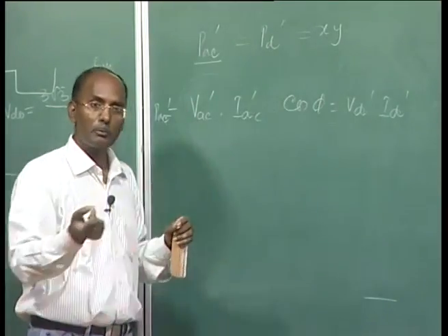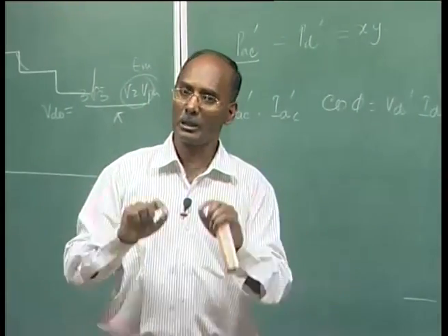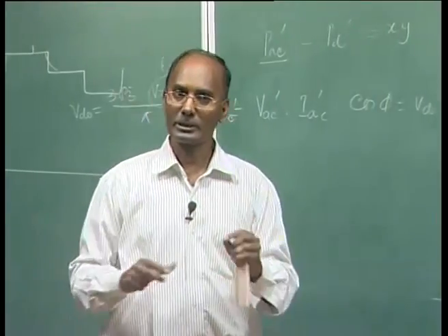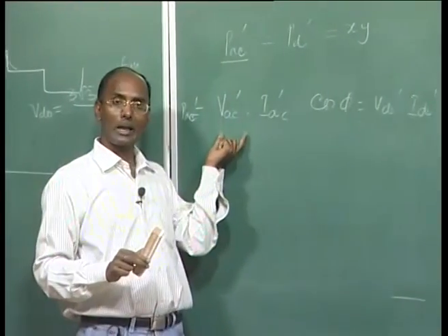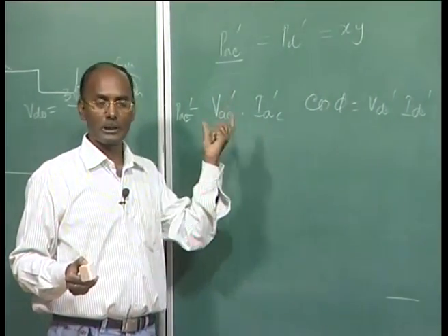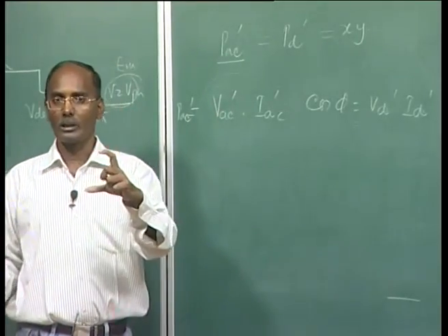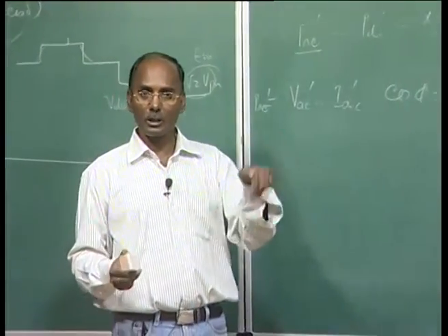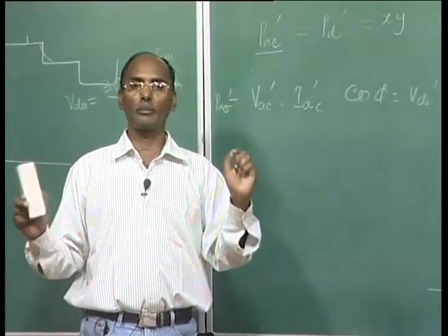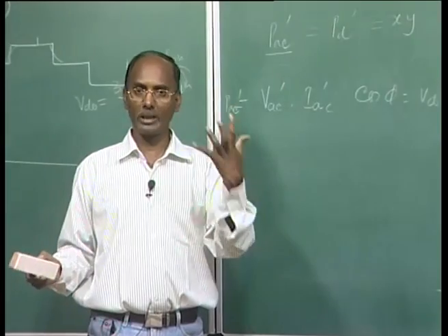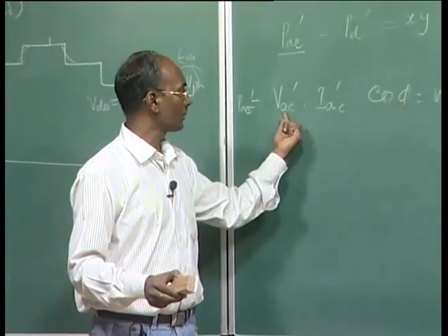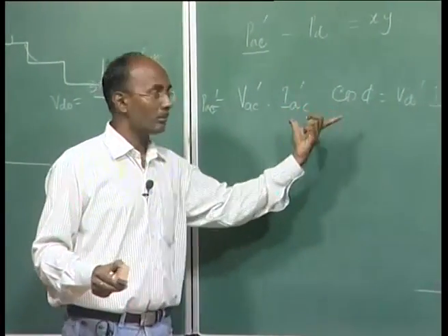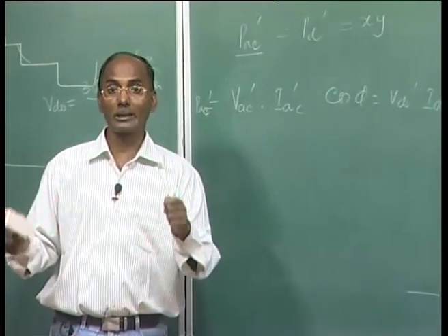So in per unit the three-phase concept has gone, it never appears. Because simply in the per unit, if you are taking line to line, the base will be line to line. If you are taking the three-phase power as a base, then voltage will be your line to line base. So that ratio, the square root of 3 and 3 terms, appear in the per unit system. Simply if your base is 100 MVA base, you multiply by 100, it will be actual power, that is three-phase power.